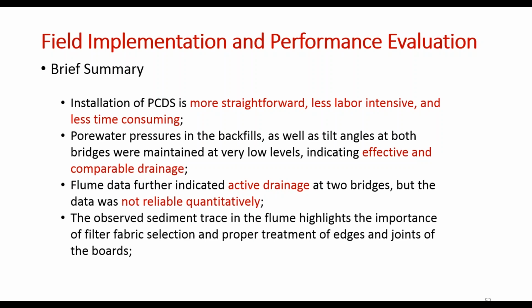And the flume data further indicated active drainage at two bridges, but the data was not reliable quantitatively. And the observed sediment traces in the flume highlight the importance of the selection of the filter fabric as well as the proper treatment about the edges and the joints during the construction of the walls.